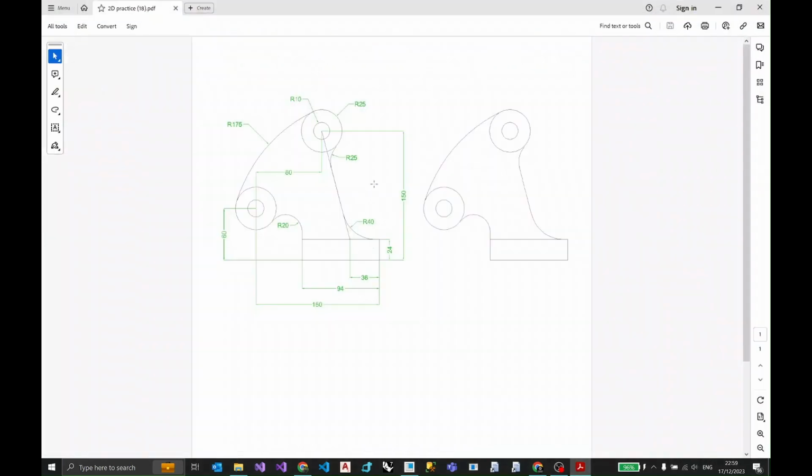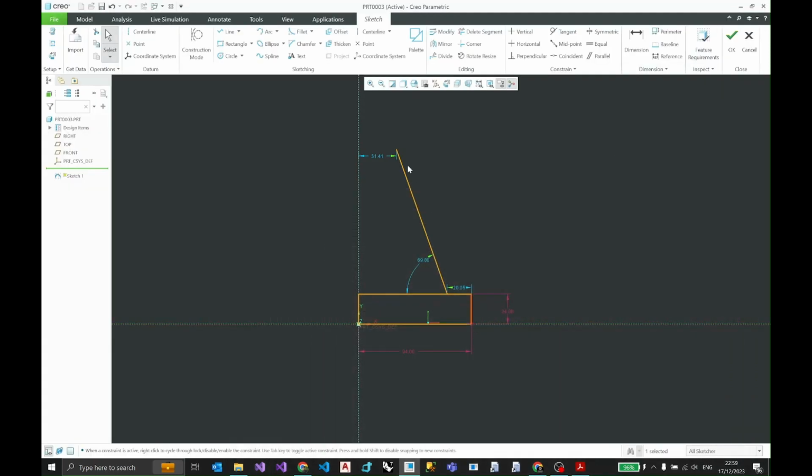So we can see that this line is pretty much defined by two lines, vertical and horizontal. So it's 36 millimeters away from this point and 150 millimeters away from this point in vertical. So I'm going to select this point and hold control and select this point as well, and go over here and select the vertical dimension, which was 150 millimeters. Lock it again, as I already mentioned, and then this dimension is 36 as we saw. I'm gonna lock this as well. So we don't need to change this angle.